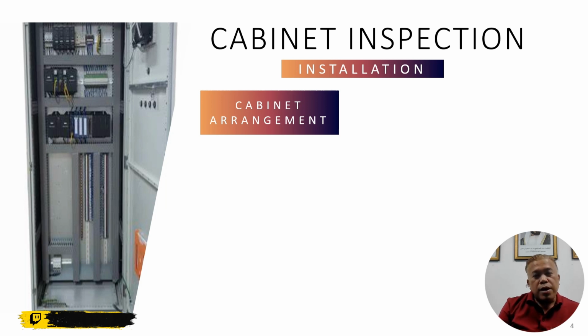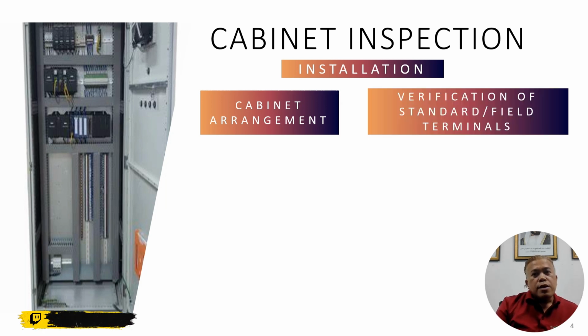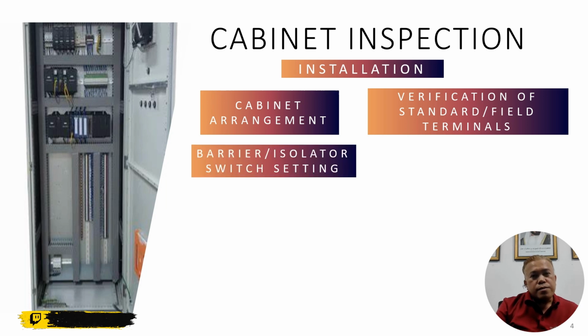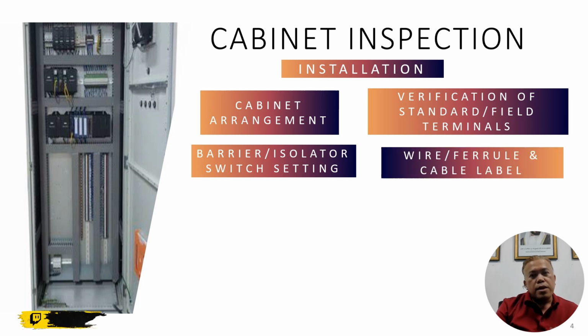You need to verify the cabinet arrangement, and the verification of your standard field terminals in that particular panel, either DCS, fire and gas, network cabinet, or ESD. You need to verify barrier, isolator, switch settings, and other parallel wiring.